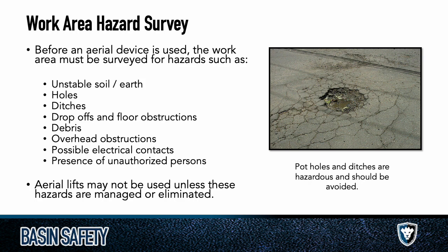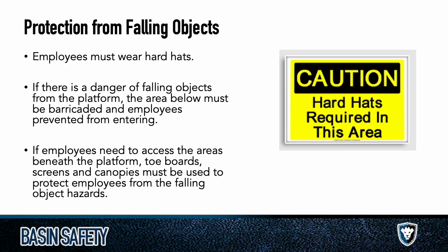All right, so moving on. Protection from falling objects, obviously people below you, and if you're working at heights, if there's things above you, this is something you want to keep in mind. Definitely don't let guys, don't let is probably not the right terminology, but talk to the guys you're working around and inform them not to walk under the aerial lift because it's a possibility you'll drop something.